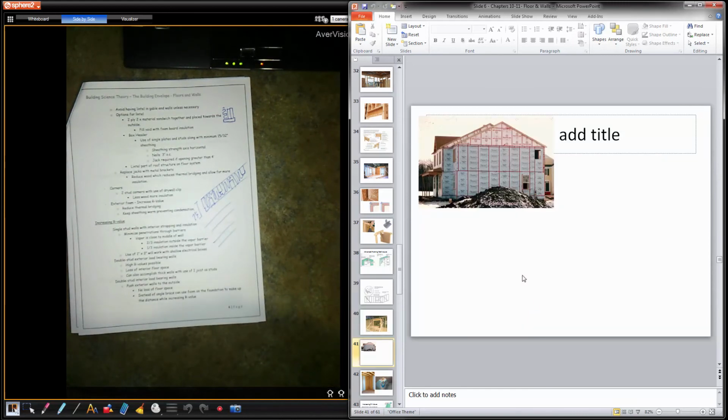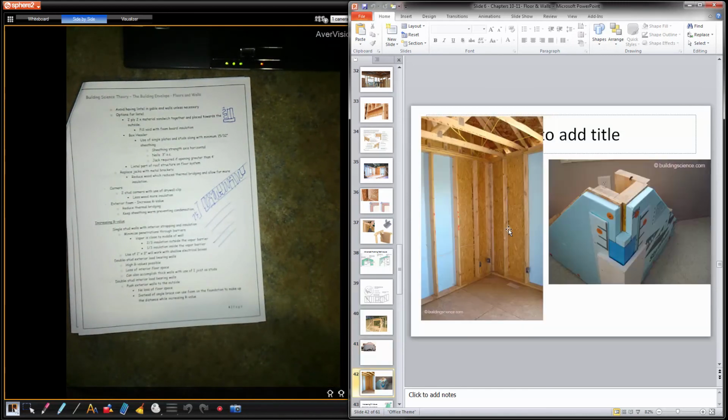So there's just the foam sheathing on the wall. There's showing the wall with the sheeting in the corners, foam coming off of it. How do you treat the foam in the corners? So normally it's flush to flush, then you put a little piece in the corner. Otherwise it screws up all your layout. Right? If you lay out something for 16 inch on center or 2 feet on center, typically that goes from the frame. So that's where you want to start your foam from to make sure it lands on a stud.